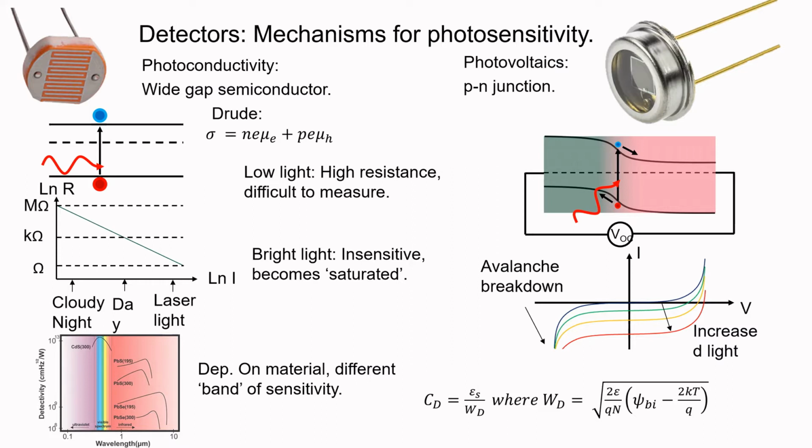Of course, you're also reliant on it having a band gap that is suitable for detecting the wavelength of light that you're interested in looking at. So again, that can limit the operating range, and you have to choose the right sort of material. And again, with any kind of semiconducting material, you have to be careful that you don't have impurities in there, because they'll create states that sit inside the energy gap that can then act as places where the charge you've created can either recombine quickly, or else where you don't necessarily create an excitation that you were expecting to.